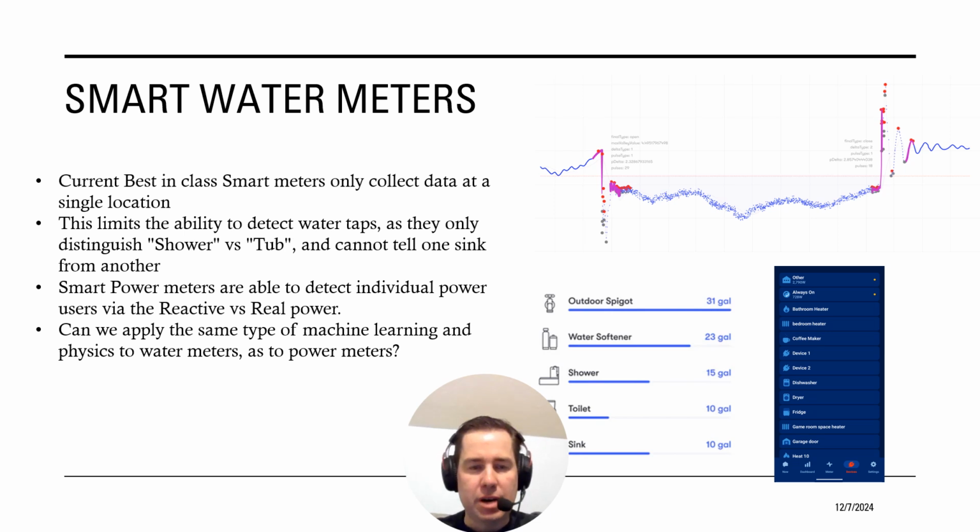This project was started by my electrical home devices being so much more intelligent than my smart water meter. The best-in-class electrical smart systems like Sense or Span are far more advanced than FIN, the best home water monitor. Smart panels have multiple voltage and current sensors that allow them to see both the active and reactive power, generating a unique profile for every device in my house. Water meters only have a single unit, mounted on one pipe, meaning every device will generate an identical pressure and flow rate, meaning we can never distinguish between two sinks in different bathrooms.